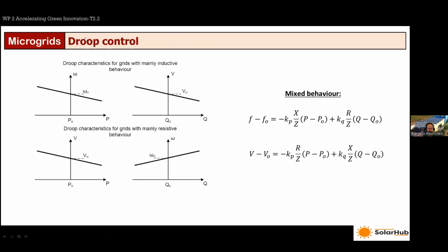So yeah, these are inspired by the operation of power systems and the performance of electromechanical synchronous generators. No need to go into too much detail. What is important to take away from here is that an inverter can be programmed to change its frequency depending on the amount of power that it produces, or vice versa. It could change the power that it injects depending on the frequency. This functionality can then be used to support the system operation in terms of balancing and frequency control.